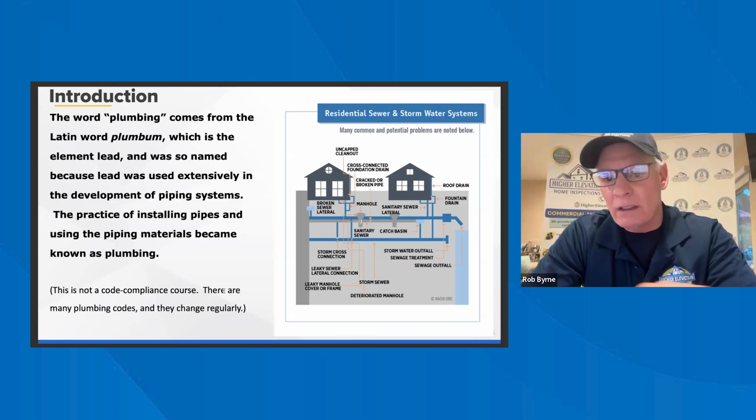TPR valves, great picture with the illustration. We do not operate these. Do not operate them, because they'll stick and you'll get stuck in that position. You don't want to deal with that. You do want to check that it's not leaking. You want to make sure that you got the extension pipe coming down to whatever, like 18 inches off the ground. But again, common sense, if it's 16 inches or as long as they get it down to where if you're standing in there and this thing releases, you're not going to get hit in the chest or the abdomen with it. You want that to be directed down to the floor at the lowest point possible.